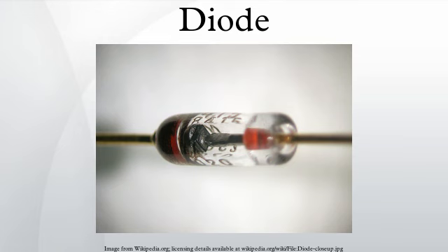Under reverse bias voltages, the exponential in the diode equation is negligible, and the current is a constant reverse current value. The reverse breakdown region is not modeled by the Schottky diode equation. For even rather small forward bias voltages, the exponential is very large, since the thermal voltage is very small in comparison. The subtracted 1 in the diode equation is then negligible, and the forward diode current can be approximated by the use of the diode equation in circuit problems as illustrated in the article on diode modeling.